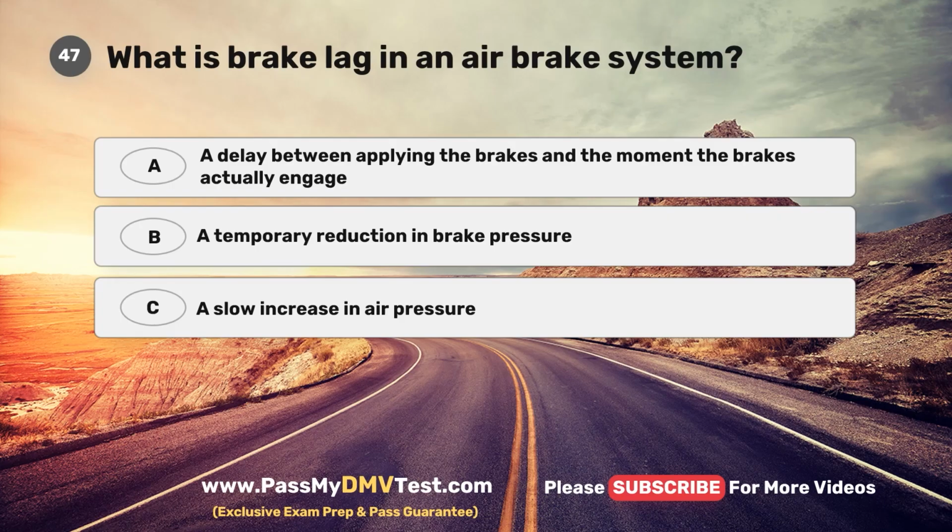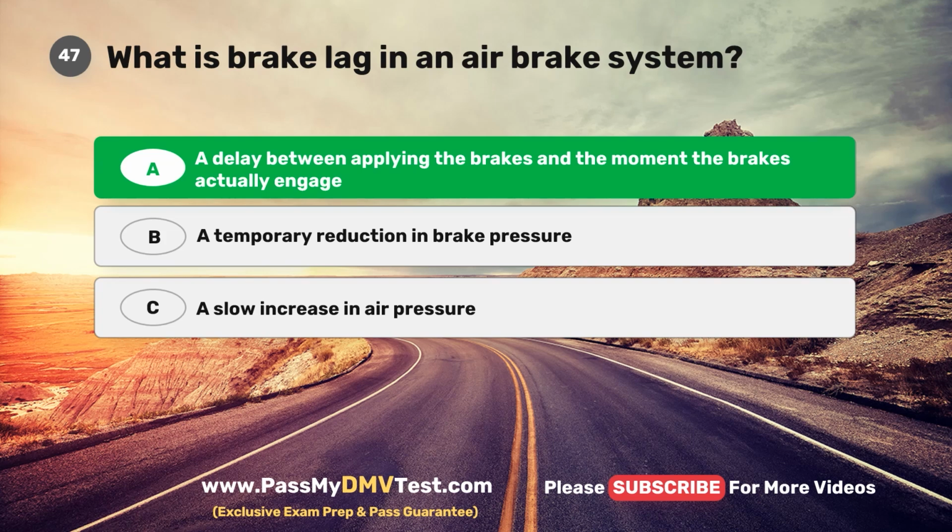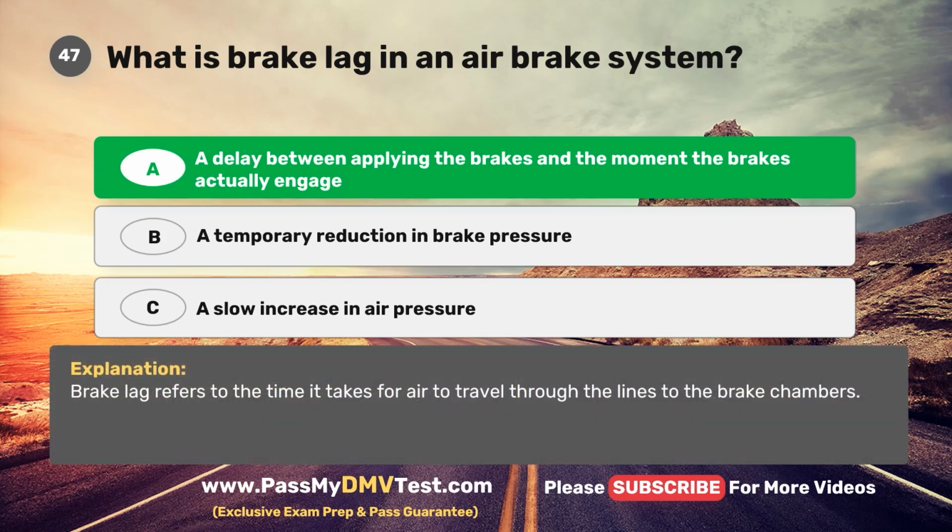Question 47. What is brake lag in an air brake system? A. A delay between applying the brakes and the moment the brakes actually engage. B. A temporary reduction in brake pressure. C. A slow increase in air pressure. The correct answer is A. A delay between applying the brakes and the moment the brakes actually engage. Brake lag refers to the time it takes for air to travel through the lines to the brake chambers.